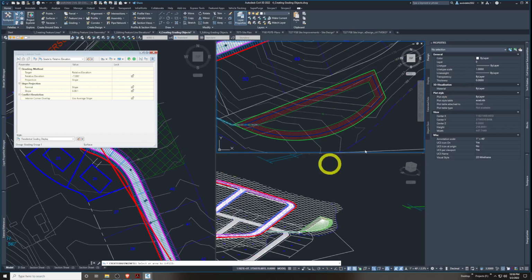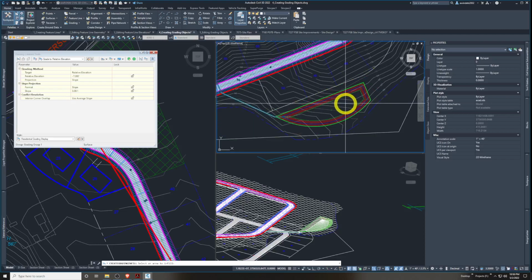So have an enclosed one on the outside and then one on the inside, and it will infill it in some manner. So with everything still open and going here on my grading creation tools, let's change our criterion to grade to distance now. All right. Well, actually, before I do that, I've already created my infill. Let's hit escape. Let that accept.